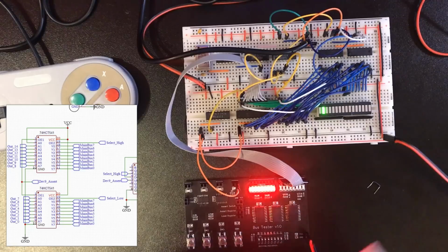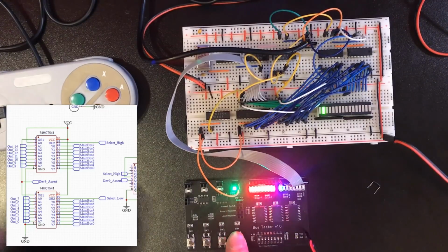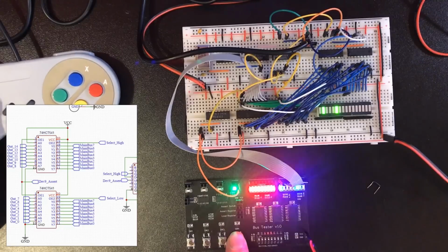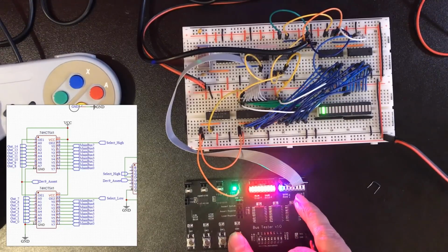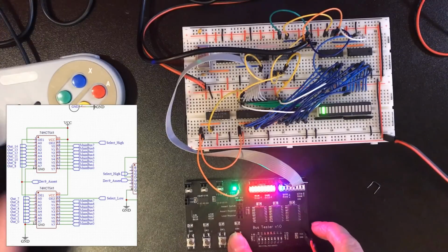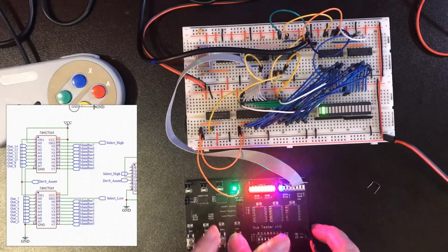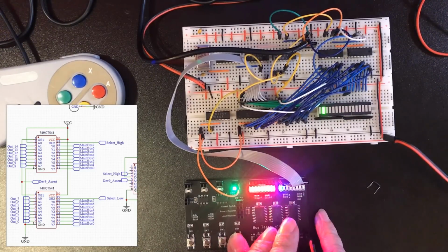Now there's only a couple of small things we need to do to this circuit to finish it off. Now firstly, I'm outputting there, so this is the high byte, but as I change these buttons, it's going to change the output state. So if I push a button while this is asserting to the bus, we're going to be changing the value we're pushing onto a bus, which is not good.